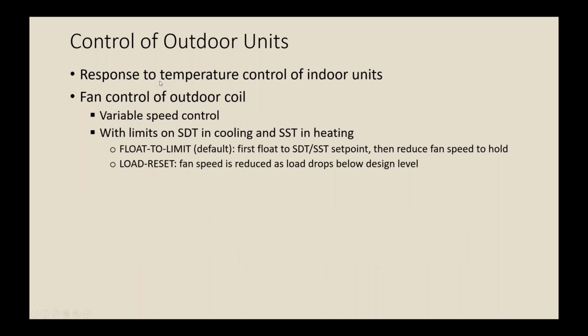For the outdoor units, the first control is in response to the temperature control of the indoor units, those temperature control scenarios I just mentioned. And then the other angle on the control of the outdoor unit is the fan control for the outdoor coil, and that would be a variable speed control. That's standard for all the systems that I've seen.